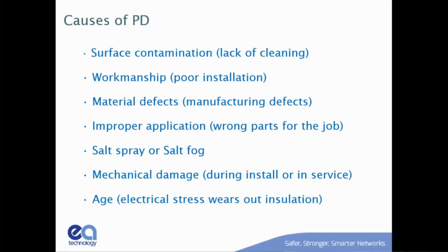They're in a nonstop battle. So if you do any work along the coast, go out to Tybee Island, I imagine they've got bigger problems than you've got in Atlanta, say. And there's always damage. We see a lot in wind farms. Wind farms are a pain because they've got a lot of cables. And unlike utilities or big industrials, they are built to last 5 years, because that's when the guy who built it is going to sell it. He's going to use the cheapest materials. He's going to use the lowest skilled joiners. He's going to bury the cables directly in the dirt instead of putting in a sand bed and all that.